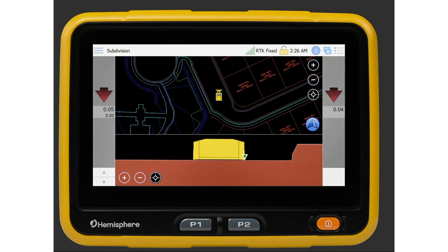Below the left light bar, you will see the up and down arrows. If we click on the down arrow, you'll notice that the offset numbers change by 1/10 at a time. The upper number here is showing you how much cut or fill you have, and the lower is our offset. The cross-section view also has a new line going across it that represents our new grade.